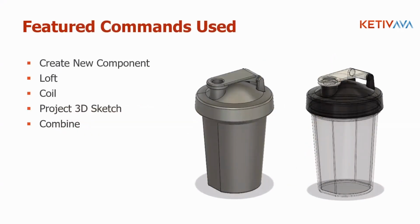Moving forward, featured commands used. These are some of the commands that I use on this model. Create new component, that's just going along with how to start the assembly. Loft, so if you see the bottom of the part is not perfectly circle, and it lofts up to the top part of the bottle. And then we're using the Coil and Project 3D Sketch tool to create our own custom threads, as well as the Combine tool to do a Boolean operation for the inverse of the thread, which is for the lid and the bottle.